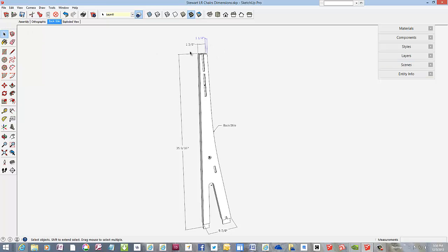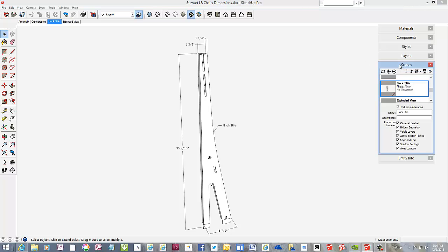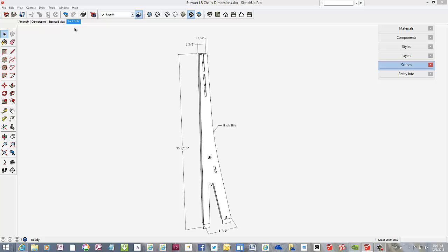With the select tool then, I click on all the dimensions and text holding down the shift key, and then click on the layer toolbar to move all of these dimensions to the perspective layer. I'm not messing with layer 0. All the graphics continue to be on layer 0. The only thing I'm changing are the dimensions. I just noticed I've got the back style scene out of order, so I'm adjusting that.